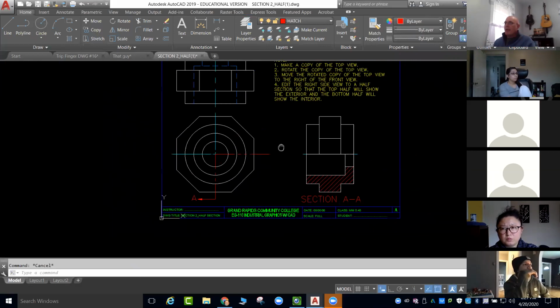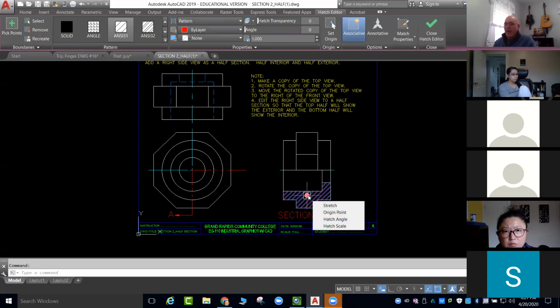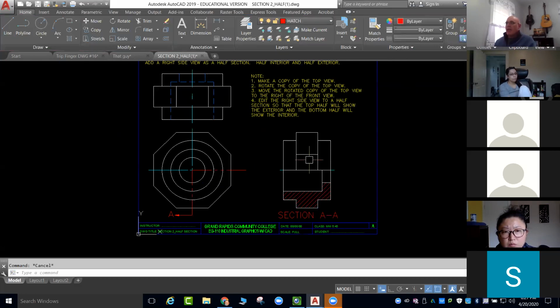Now if I zoom out a bit here, I can see that what I have here is still the same surface that I have inside where it's hidden. Out here, I can see it as visible. And remember, the whole purpose behind section views is to remove hidden lines. We have no hidden lines in section views. So I'm just seeing the outside edges of the union. So my surface here represents my surface here. This little smaller block represents half of this edge. So now I'm only seeing that inside.